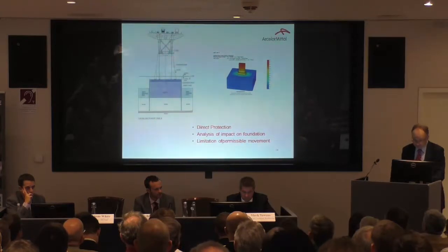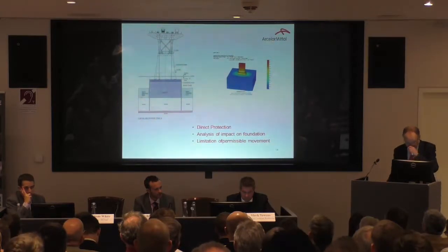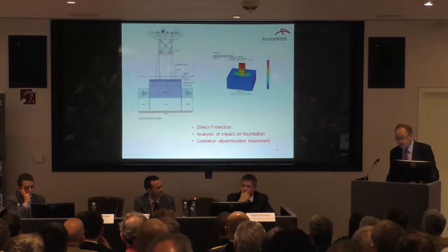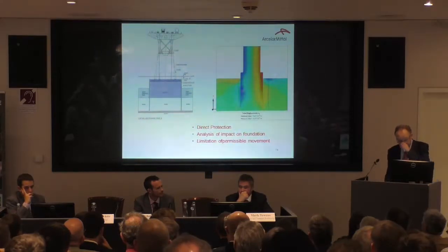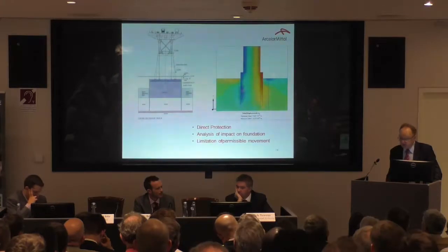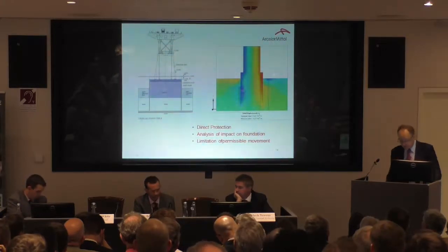And the FE analysis works out the resultant forces of impact, 30 meganewton over 6 meter spans, to give resultant deflections and energy absorption facilities, with the piles embedded to fixed embedment.